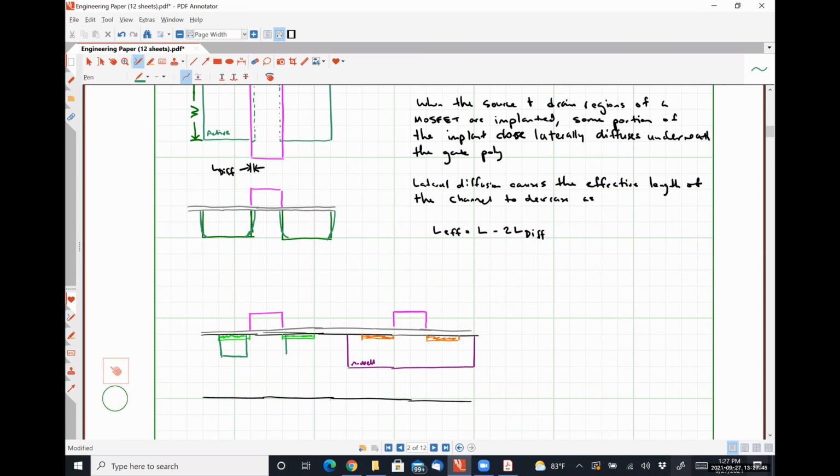What's going to happen is that my normal dopant implants see those incredibly highly doped implants and say, well, since that's a higher dopant concentration, I can't diffuse in that direction. So you just get that little bit of help underneath each edge of the polysilicon layer from those extremely highly doped implants, which cause that reduction in threshold voltage and in turn help strong inversion happen more easily.